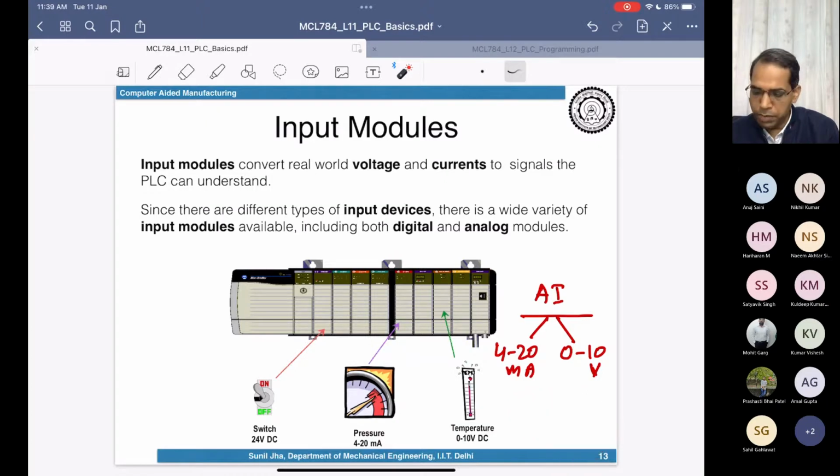So this drop is very critical when sensing that particular parameter is important and you are keeping the sensor far away from the controller. Whenever the sensor is far away, we never go with voltage as the output option. We prefer to have the current output from the sensor.